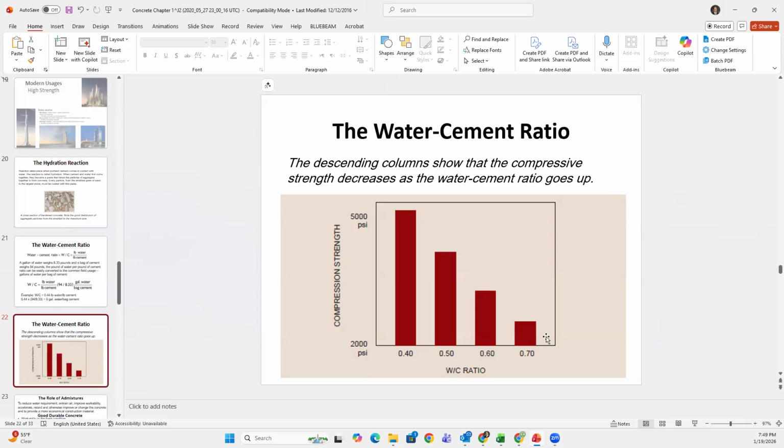You already learned the stuff you put in your soup: your rocks have to be granular. You learned your sand cannot have salt, cannot be beach sand. You learned about your water a little bit. So you know enough now to catch somebody who is using river water, sand from their backyard, or rock from the river on their property to make concrete. Does this happen all the time?